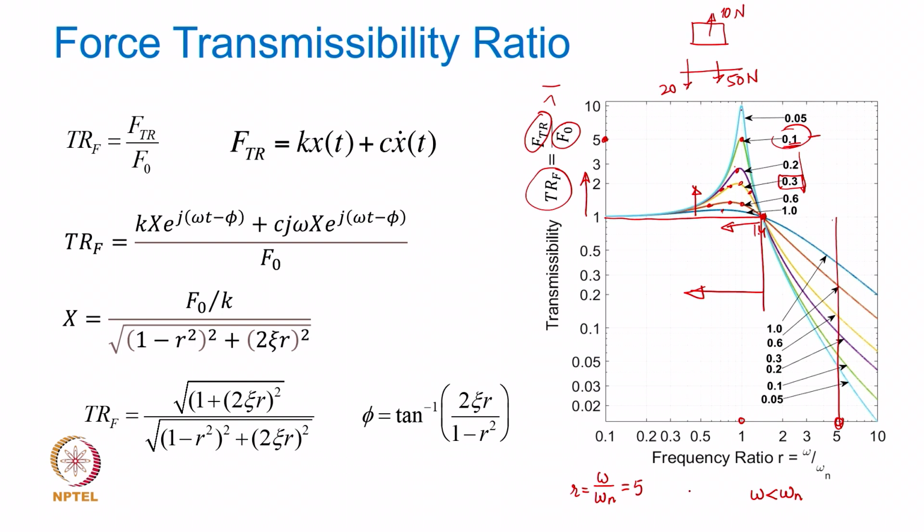That this condenser unit mounted on the mounts here, the natural frequency of this entire system omega n, if that omega n is 1/5 of the excitation frequency, you can see that this omega n is omega over 5.